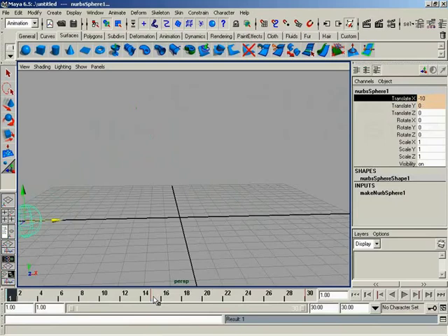And finally, we can move keyframes around as well. We can simply hold the Shift key down. Make sure our timeline is on an indicator. As Zach just said, you see how we have the cyan color. That means we're on this keyframe. Hold Shift, left click. We get a series of arrows, 2 pointing left, 2 pointing right. One set of them is for scaling. The other set of them is for moving. In this particular case, don't worry about the scaling. We'll talk about that stuff later. But I'm going to use my inside arrows, and I can move left. I can move right. And as I do this, I am changing my timing for the animation.